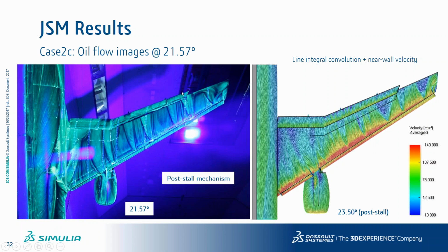But as you increase again to a higher angle of attack, you can see that the separation still occurs. We've got the nacelle separation occurring, going against the near-fuselage separation area and also the wingtip separation here, which occurs again pretty nicely as in XFlow. So it seems the stall mechanism is correct. It's not that we see the main separation area occurring at mid-span or something. It really occurs in the critical regions that are described in the flow field by the experimental facilities. Okay, so that helps us understand if we're predicting the stall for the fundamentally correct reason. It seems it's okay. So again, a slightly over-predicted region close to the outboard flap, but overall it's pretty good.